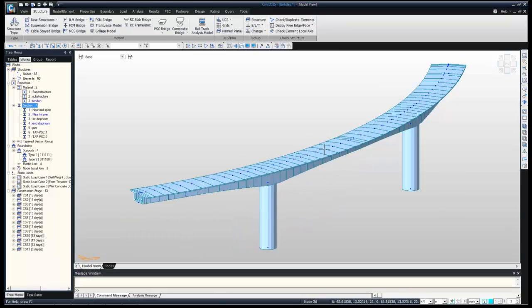So what I mean is, the wizard we can use for quick modeling, and later if we have some modification, like, let's say this element, if I just select, this is the select option here. If this element is varying or is different at the end or something, we can just directly change the section. We can just directly drag and drop and assign this section.